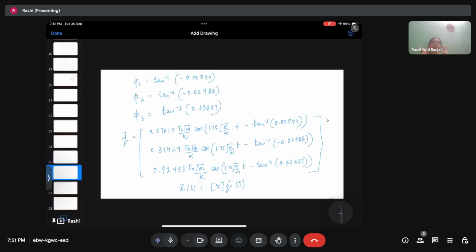What is important to note is that mode shapes and modal frequencies play a role only if my system is undamped. Once my system becomes damped and a forcing is applied, there is no point discussing the modal frequencies, because every single mass of the system is going to oscillate with the forcing frequency only. In the steady state solution, that is the case; it will definitely have the contribution of the natural frequencies, or modal frequencies, when the system is in the transient phase.